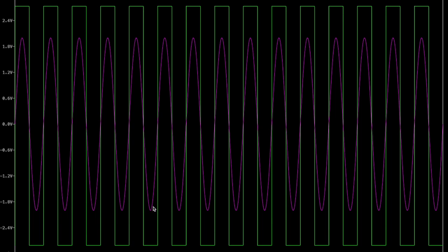The main portion in the Schmitt trigger, however, is in the neon green graph. We can observe multiple things. Firstly, the output is very clearly a square wave, characteristic of that of a digital output. This oscillates between positive 2.8 volts and negative 2.8 volts.